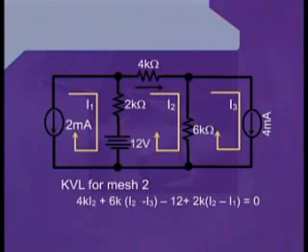As we reach on to this wire, we encounter the 12 volt independent voltage source. And to the other end of the 6k, we can see that the negative terminal of the 12 volt battery is directly attached. Therefore, we may well write as minus 12. After writing this term as well, we pass through the 12 volt source to reach at the wire which is between the 12 volt positive terminal and the 2 kilo ohm resistance.